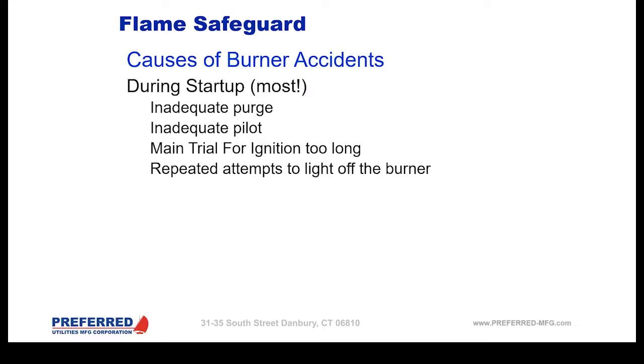Obviously, we have purge and post-purge to do as much as possible to get the fuel out of the combustion chamber. But when we start talking about oil burners, for instance, there have been a lot of accidents where people have continued to try to light off a burner, and you just can't possibly purge it enough. At some point in time, it has to be serviced, taken apart. So the most dangerous time is during startup.